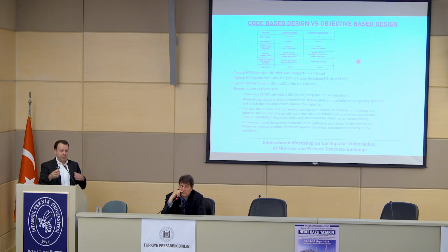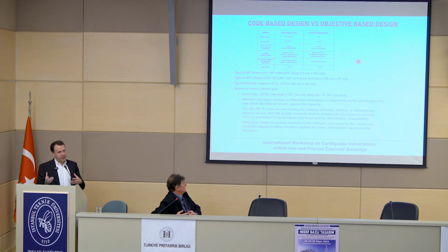And so for the columns and the beams, you still have to detail them very, very well so that they can capture that deformation, but we're not counting on them for strength capacity. That's for the lateral resisting system. And maybe I should add that we don't consider this a dual system. A dual system would be a dual lateral resisting system, but I understand what you mentioned. You can also, so my third bullet point there, explicitly model them, right? But often they're not considered in the modeling and not considered analytically, but we check that all those connections can withstand the deformations.